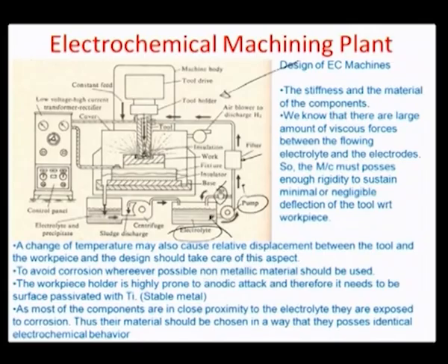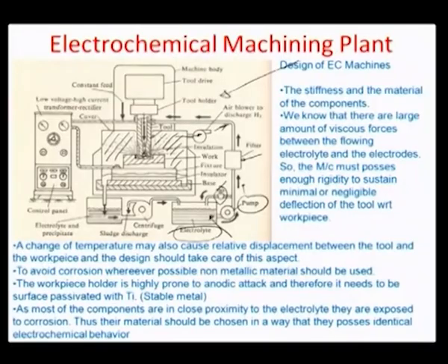As such, it discharges whatever hydrogen or gases emanate from the tool side. There should be a capability of blowing them out. So this environment being closed, whatever hydrogen or ammonia is generated as a sub-process on the tool side, okay, where all the ion transport would happen, that gas can be discharged. So there should be a discharge port for the byproducts of the chemical reaction coming out.